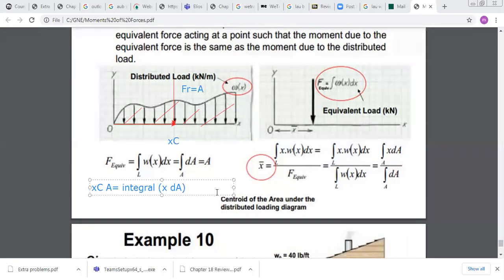So I have integral x dA. Here in this problem, when we did the expression of the location, we obtained that distance d is equal to integral x dA over A. So we can say here that the distance d of the point of application should be equal to, in my problem, I demonstrated that d is equal to integral x dA over A. But if I look at the expression of the centroid from the mass relation for centroid, if I do integral x dA over A, what do I get?